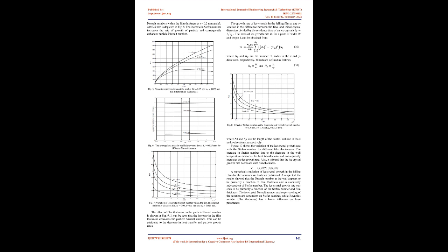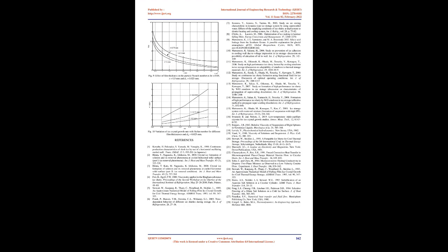However, the solution temperature decreases along the x direction and the temperature gradient at the wall and the heat flux increase due to the enhancement in the effective thermal conductivity. The increase in the local Nusselt number in the flow direction for T equals 0.75 mm and 1 mm can be attributed to the increase in the ice particle concentration and the enhancement in the solution's effective thermal conductivity.